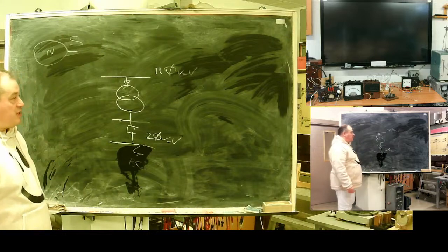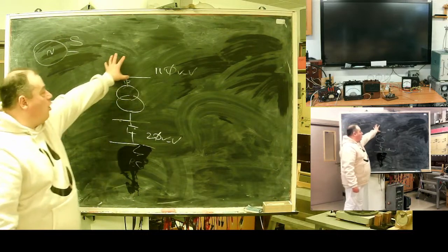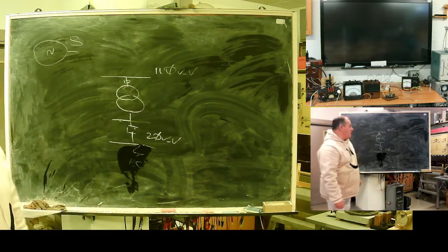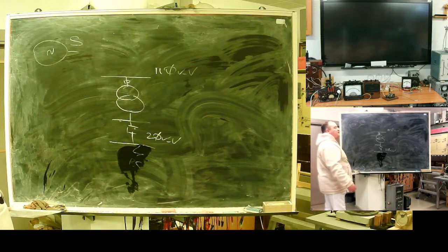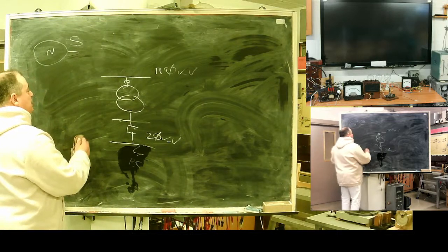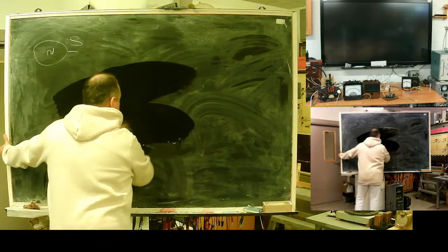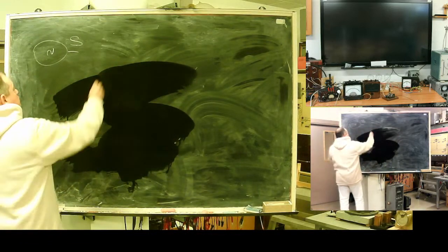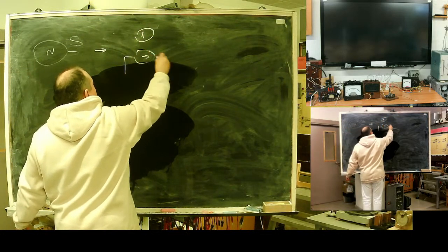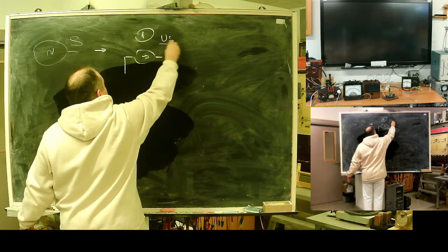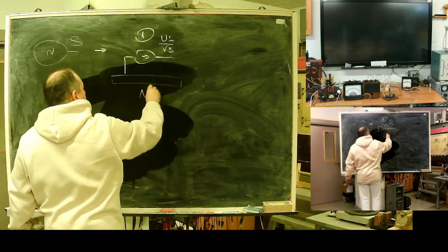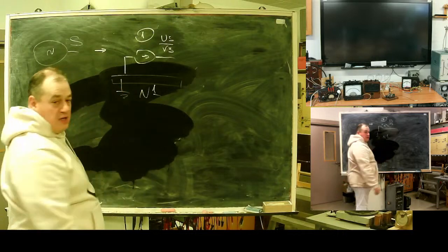Distribution networks here operate in isolated neutral mode. All the 110 kilovolt part I can dispense with or represent as a system. So the system in direct sequence will be EMF divided by square root of 3. This is the direct sequence, neutral and ground.